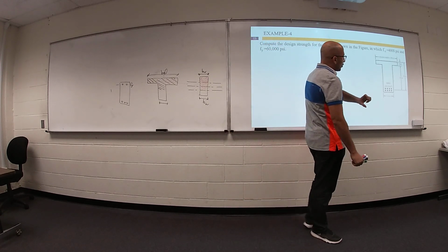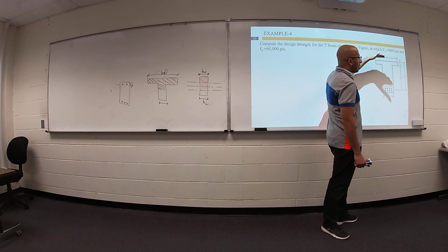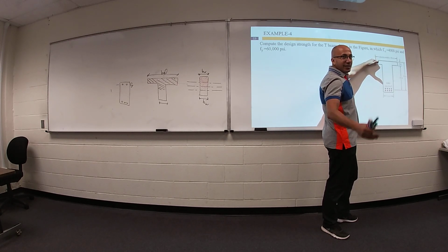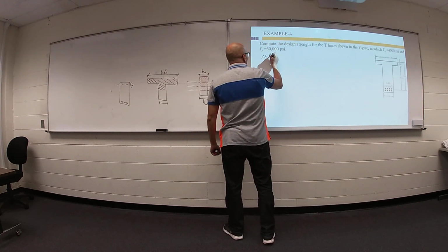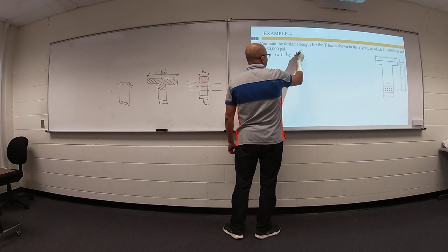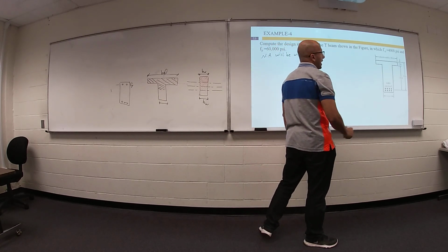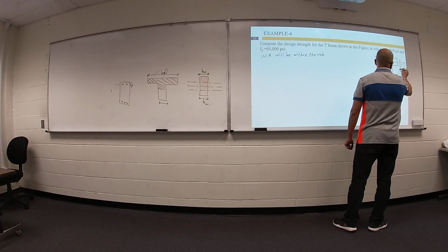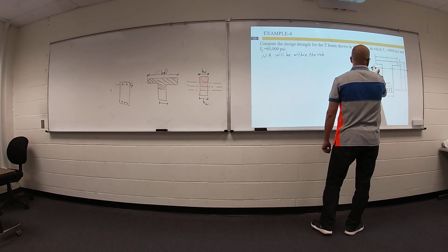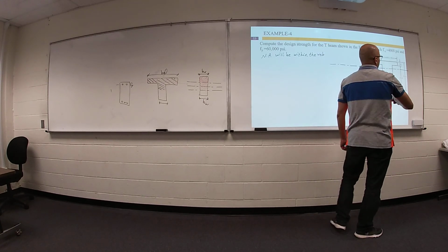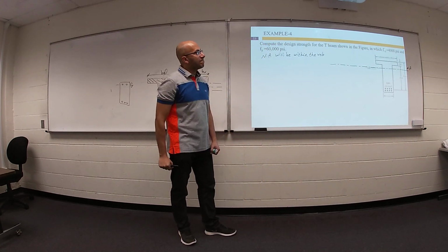Actually, we just solved this problem and we assumed your neutral axis is within the flange, and your assumption was wrong. Second step, hey, the neutral axis will be within the web, or outside your flange. So we have something like this.